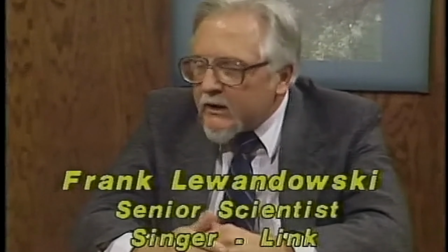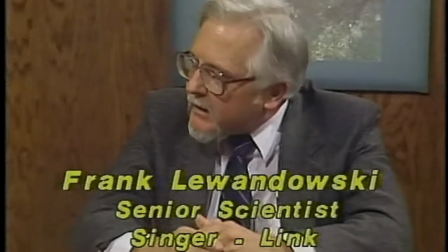No, what we're doing here, of course, is updating a scene which is made up of probably 20 or 30 lines, and you're updating it 2 to 3 times a second. Well, in aircraft simulation, if we were to do the actual scene out of the windscreen of an aircraft, we need a much more sophisticated scene than that. A pilot just wouldn't accept this kind of a scene for military training. And so we usually have to go to something in the order of 8,000 edges for every television frame time and compute a new scene each time, as opposed to here where we're doing 2 or 3 a second.